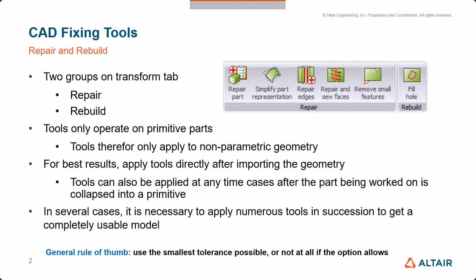When a geometry is imported into Feko, it always comes as a primitive, meaning the history of that geometry construction won't be available, and you cannot change the individual dimensions of the inherent parts. You can only apply the scaling operation that will make the overall geometry small or big.